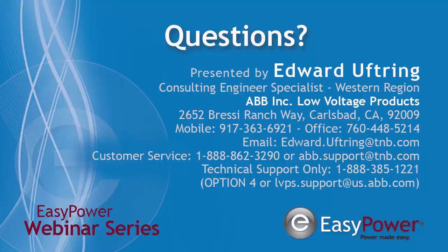This is not like the GFCIs that you see in your house, where at 500 milliamps it measures and then it opens up to protect you. This is actually kind of looking at the current, and as soon as there's an imbalance in the phase, which means that that current is going, instead of from phase to the return, it's obviously leaking somewhere.